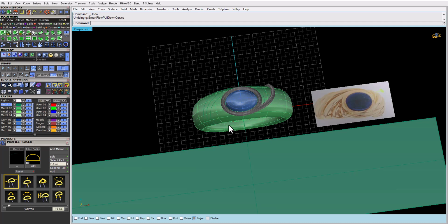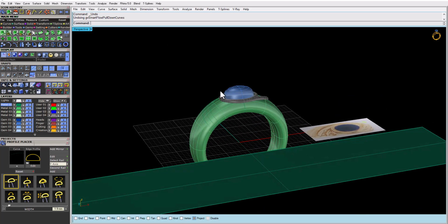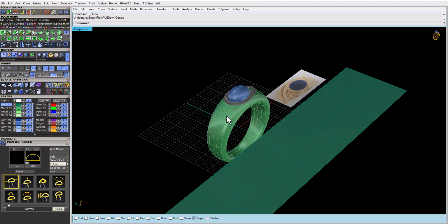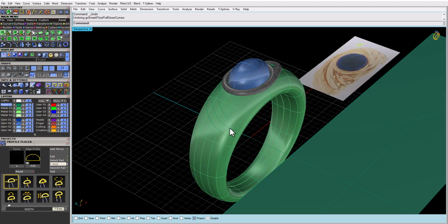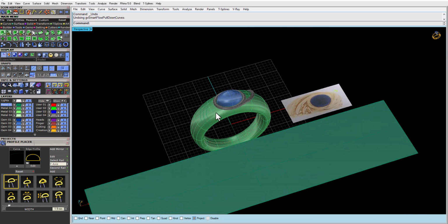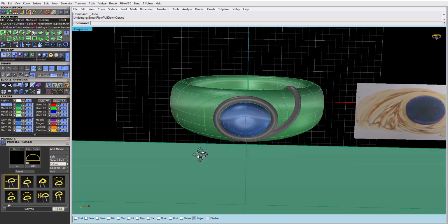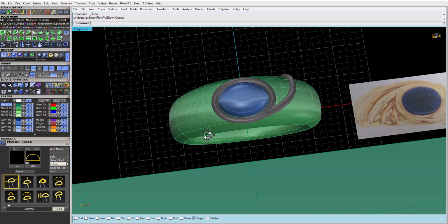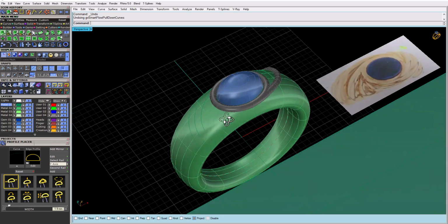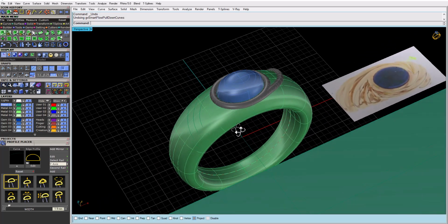I mean, it won't be the same exact dimension as what you have on the base surface. So you work here, and then you try to add the profile on the curve itself over here, and then you try to do the sweep one. I mean, that would be the closest and the easiest way to get this ring done over here.